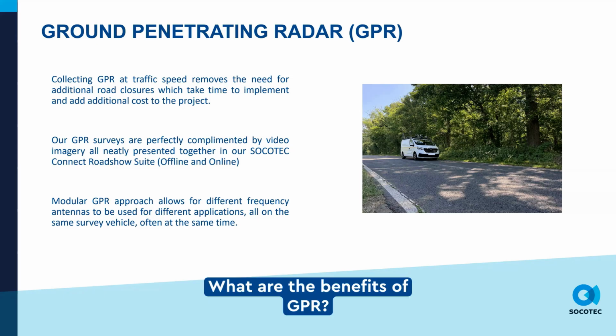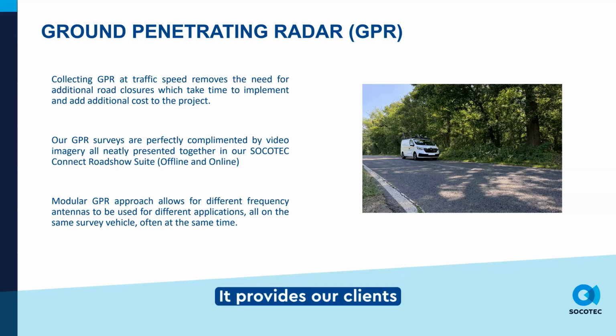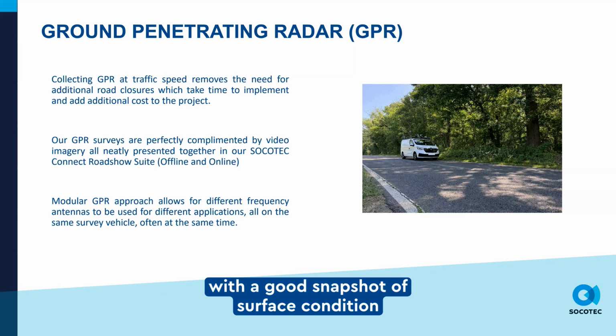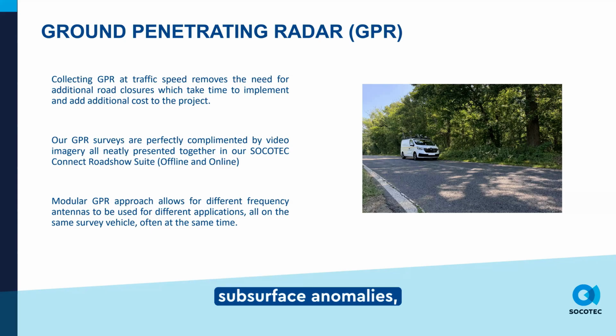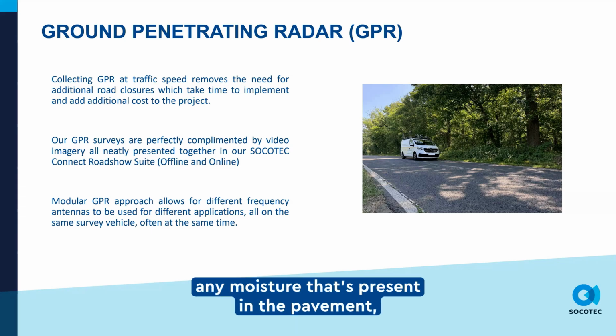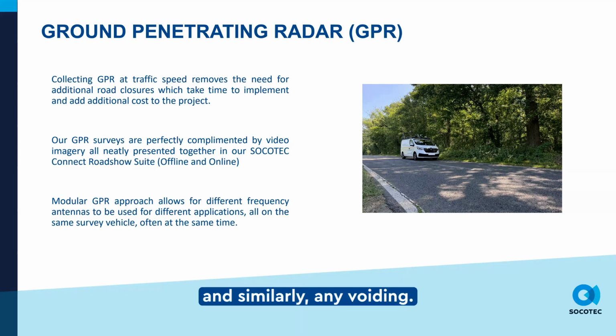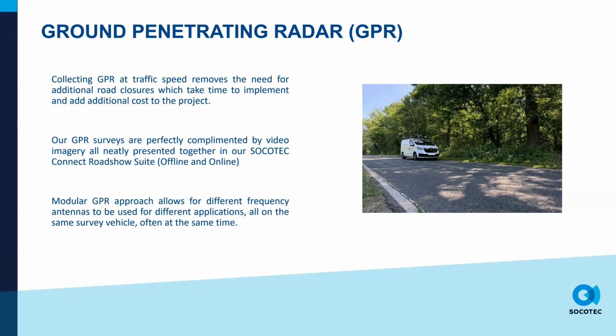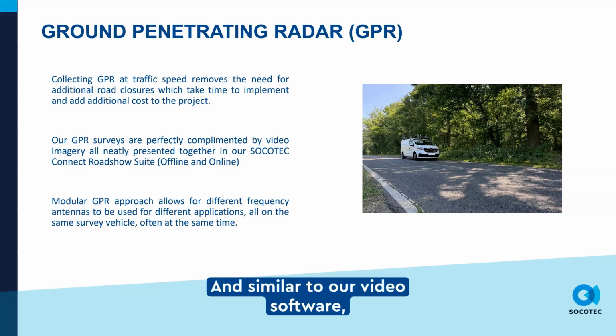What are the benefits of GPR? It provides our clients with a good snapshot of surface condition when accompanied with video. The GPR provides structural layer composition, subsurface anomalies, any moisture that's present in the pavement, and similarly any voiding. And similar to our video software, our system is fully modular, allowing different frequency antennas to be used depending on the application, often within the same survey mobilization.